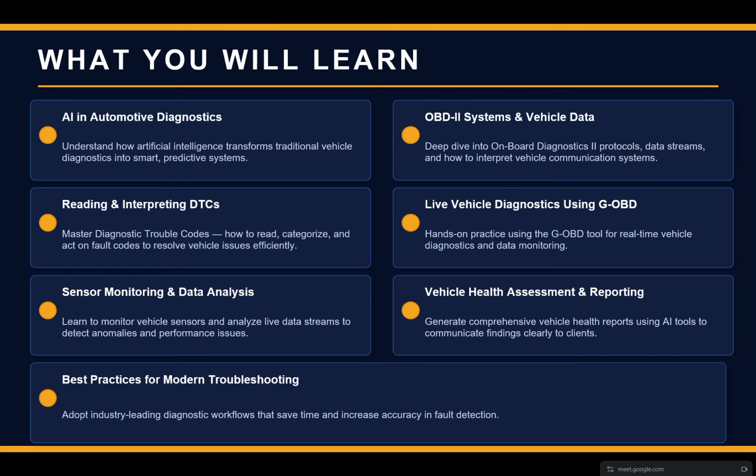So when you have multiple fault codes, and you check your freeze frame, your live data, all the signals in the vehicle, you have to take time to brainstorm and look at which is not working well, and then look at the symptoms your car is going through.